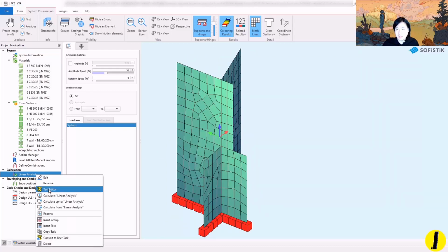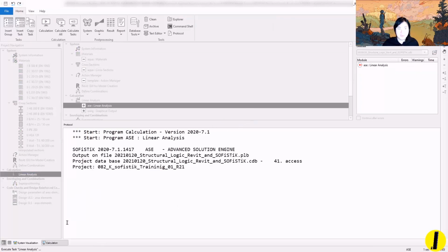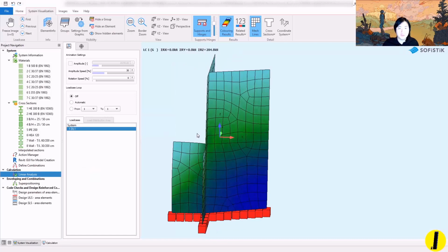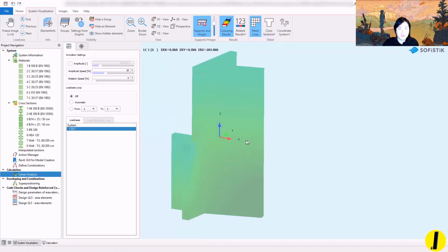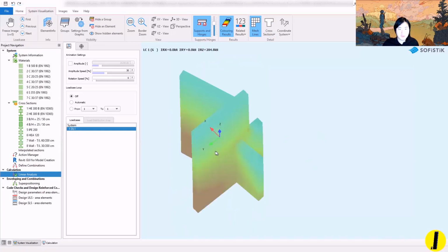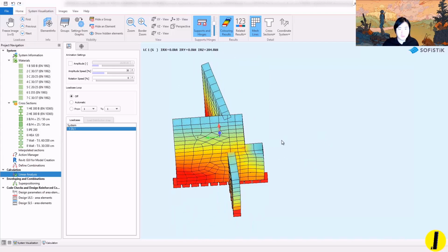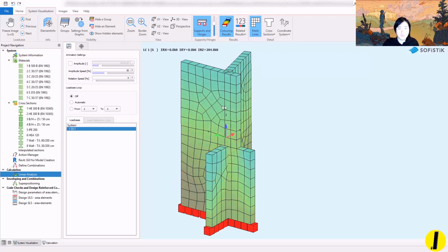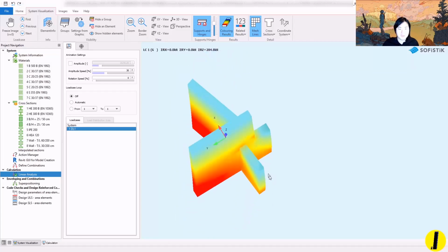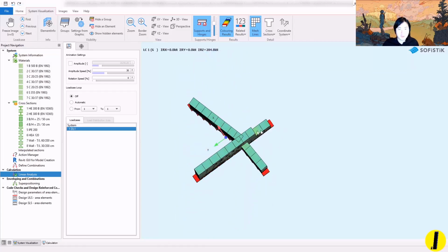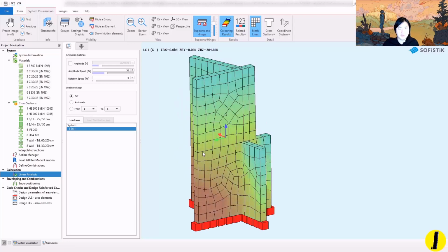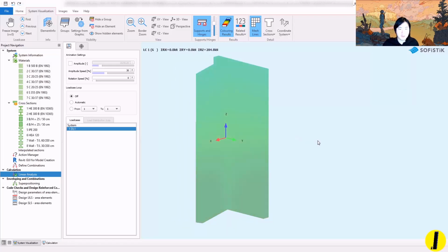And when I analyze now on the dead load, you can see deformed geometry here. Yeah, it's very logical because here we have more wall mass above, so the deformed geometry is slanting towards this direction because the self weight here is heavier, and so we have more force from there, which is really good.